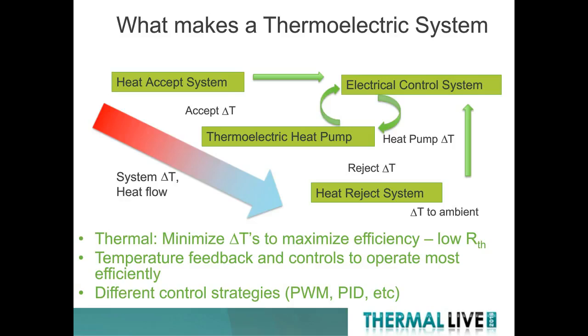Yes, historically the heat transport systems used with thermoelectrics are extruded aluminum heat sink systems. And the fin effectiveness and the overall efficiencies of those devices drive the DTs on both sides of the device, either up or down, depending on the functionality, which pushes the thermoelectric device into an unfavorable COP condition. By eliminating the losses as much as is practical on the interfaces and through the heat exchange systems, you're able to bring down the device-level DTs as compared to the system-level DTs so that they're more in favor of operation.